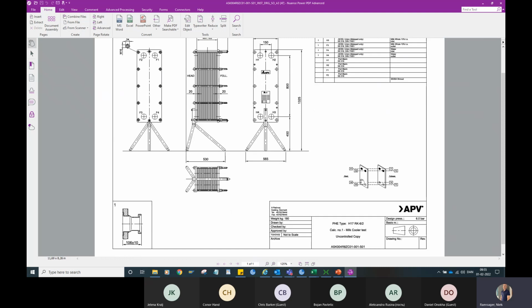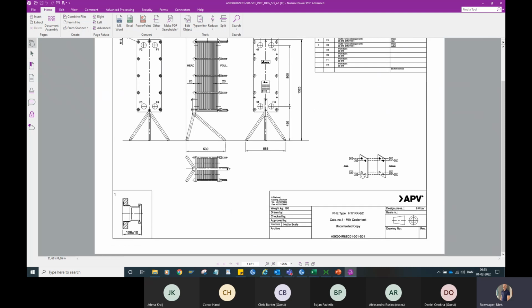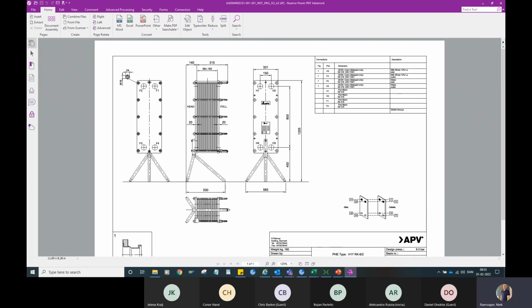and it makes a small 3D sketch down here, and the ones which are open are of course the open ports, and the black ones here are closed. Small sketch of the fittings. Not, how to say, 100% correct, because this is a standard figure that it pulls in. So even though if you select a clamp, it will still show a union, but the purpose of it is to show the measurements for the fittings. If it was a clamp, it will up here be named a clamp union.